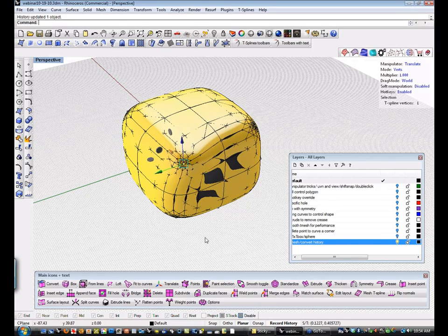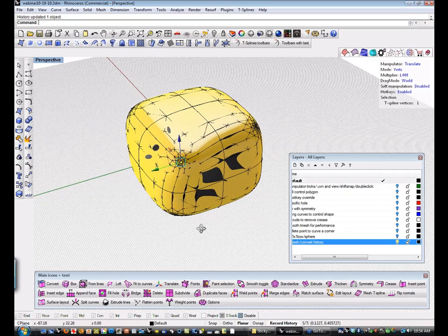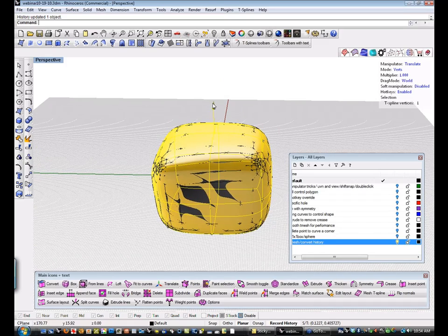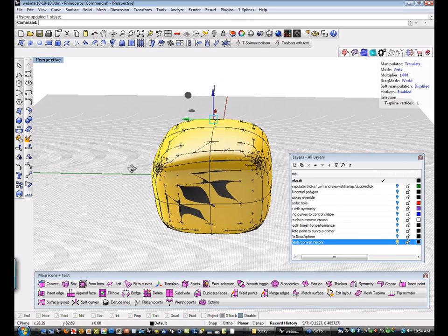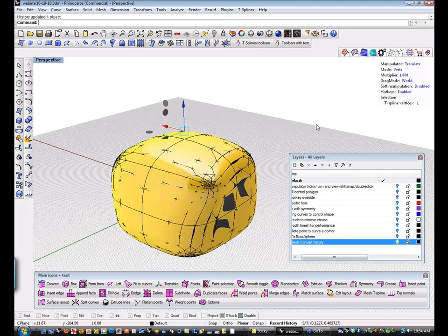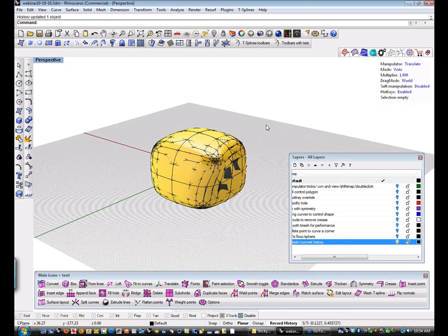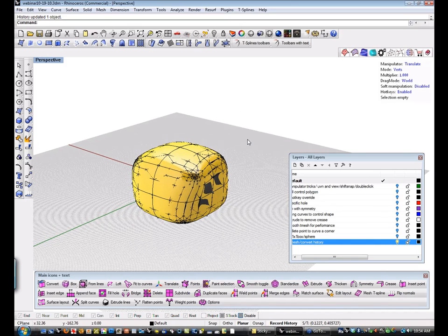Instead of having to go back and untrim the model, which is if you were doing this in Nurbs, you'd have to untrim it and rebuild everything and do all this kind of stuff. If you save this model at this point before you export your STL, all you have to do is go in, grab your point, move it a little bit, your mesh will update, export a new mesh, you're back in the vat, your batteries fit, and you're going home at 5 o'clock on Friday instead of midnight. A beautiful thing. We love that.